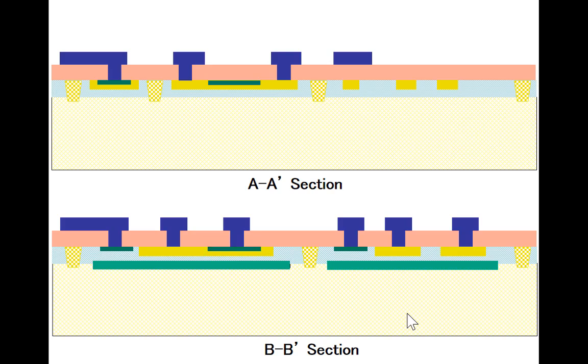For a good bipolar transistor, it's important that the base region be thin. So when you put this process together, this distance here will be small. The thinner this distance is, the higher the beta of the transistor will be. Okay.